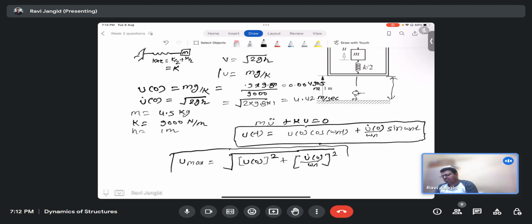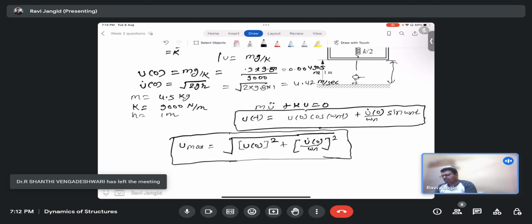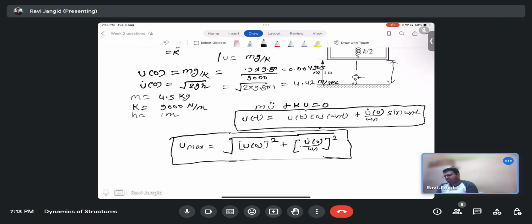Do you have omega n? You can calculate it. How do we calculate omega n? You have the mass, you have k, so you can find omega n as the square root of k by m. So please give a try to find out omega n.